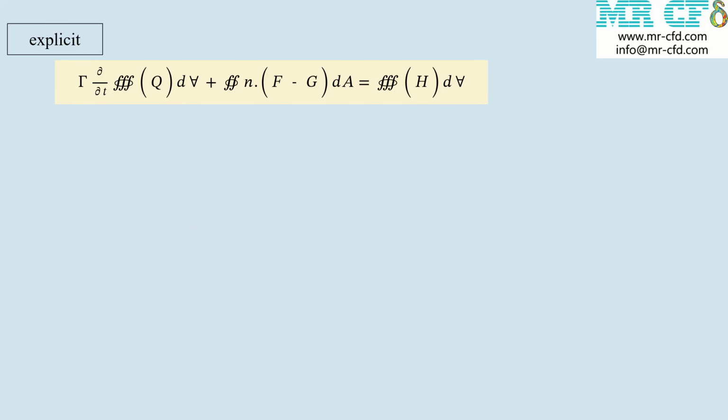Now we derive the formulation for the upstream splitting scheme, USS, and also the Roe flux difference scheme. Both of these schemes can calculate values in either an explicit or implicit manner. As discussed earlier, in the explicit formulation, only the values at the one cell are used for the next step, with all other values imported from the previous iteration. Thus, delta Q at this iteration is equal to alpha I inverse gamma delta T R to the power of I minus 1, referring to the changes from the previous iteration.